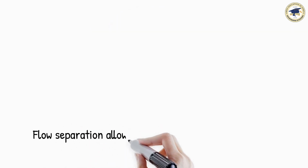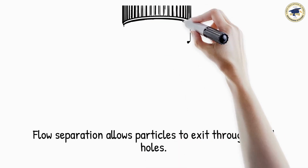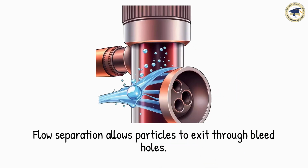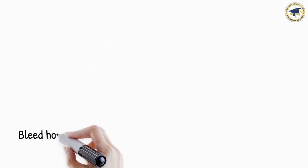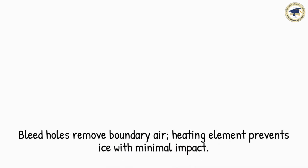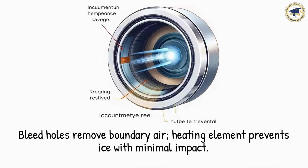Flow separation is achieved because water or solid particles have sufficient kinetic energy to pass directly through the air intake and exit the bleed holes. Bleed holes in the intake casing allow the higher pressure air escaping from within the intake casing to draw off boundary layer air. An integral heating element prevents the formation of ice. The effect of the heating element on the temperature sensed is small and is not significant.